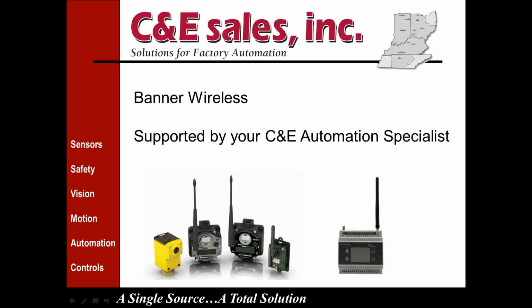Question, John says, do the nodes and sensors alert for low battery? Yes, if you're doing a battery, there is a low battery indication, but typically you want to put those on a regular replacement schedule based on the frequency. There are some calculations we can do for estimating battery life, but typically you want to put those on a PM schedule. So, once a year, once every 18 months, something like that, you would go ahead and replace those batteries.